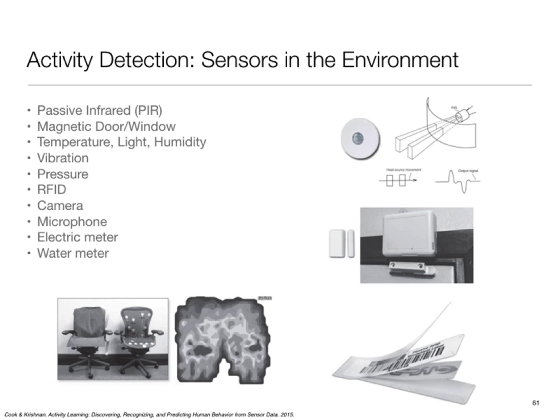And I guess the final bit, back to compressive sampling, was that there is a universal way of doing compressive sampling, which was that random matrix approach. If you think about a matrix as nothing but a linear transform, all transforms do is map it into a different space. So we are mapping it into some space, and it turns out that these random matrices preserve the information, but let you sample it in that nice manner so that even with fewer samples, you are able to recover the original signal. Okay.